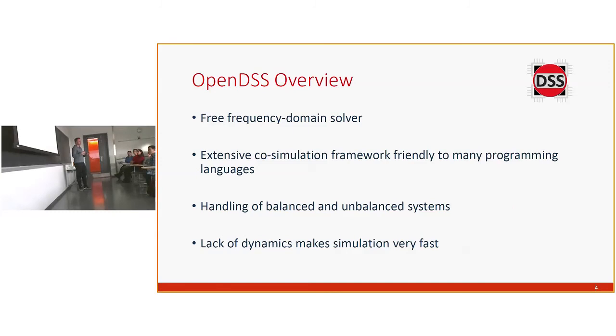Just going over a little bit of what OpenDSS is. It's free software, open source, and it's a frequency domain solver for power systems. The real bonus here is its extensive co-simulation framework that it has. For all intents and purposes, it gives you a library that you can use in programming. So you can use it pretty much with any language that you would think to use: MATLAB, Python, C, all of those. In this work, it's been done in Python, or in MATLAB. A little bit in Python, but that's not being presented today.